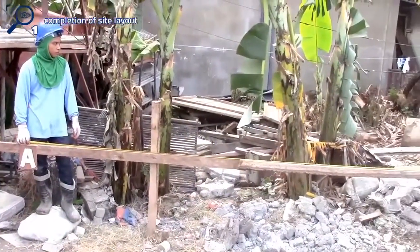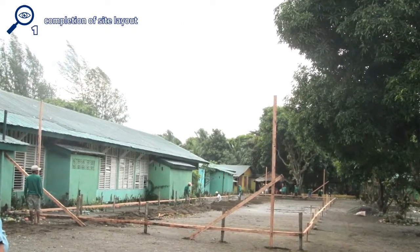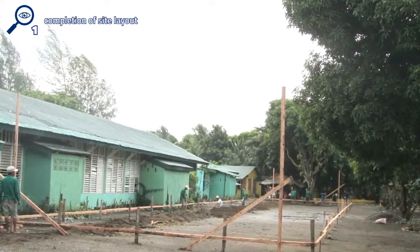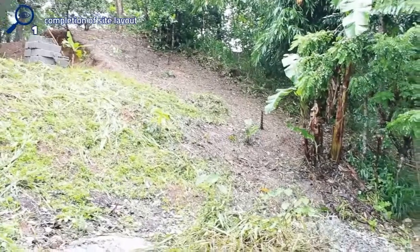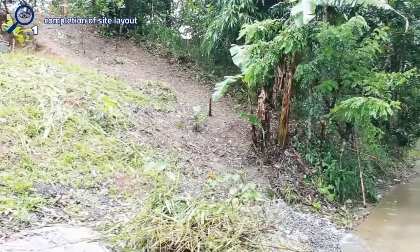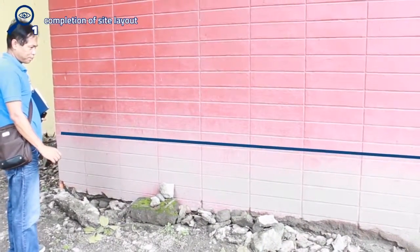During the inspection, the engineer must verify that the site marked out on the ground is as per the site development plan, that the site as now marked out conforms with the site appraisal report, and the engineer should validate the data in the site development plan. It is also important to ensure that the site complies with any requirements due to sloping ground as identified during the physical site inspections, and the floor elevation will comply with the maximum flood level recorded in the area.